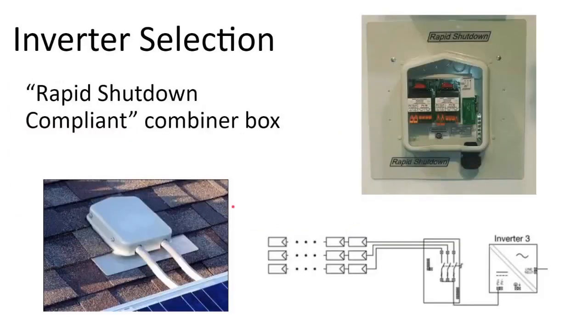Where some of these line diagram creation tools fall short is the balance of system material, wanting you to detail exactly what it's going to be out in the field in construction. So for instance, here's a popular rooftop transition box that's for transitioning the cable to go down into the attic, and being able to interrupt these home runs and say, no, right here, I want a junction box to transition into the interior of the attic. Sometimes that level of detail needs to be re-highlighted in CAD.